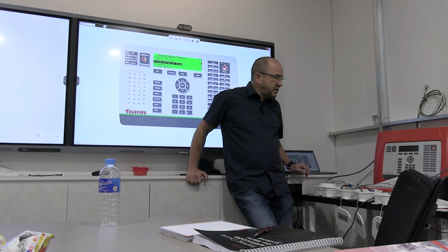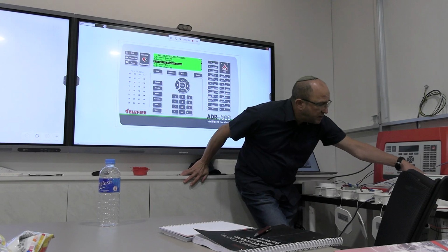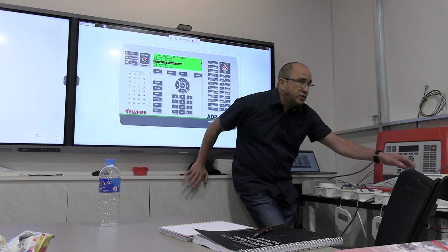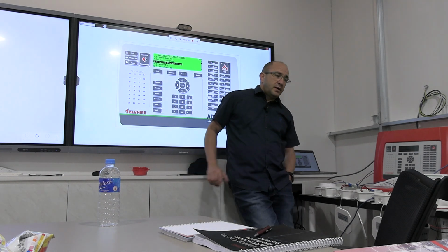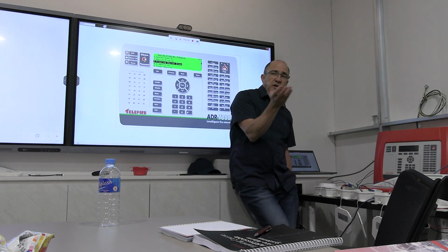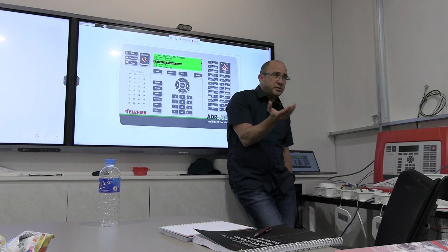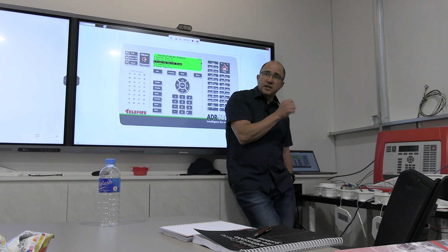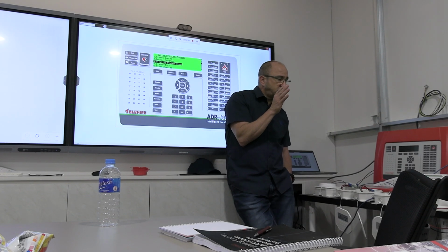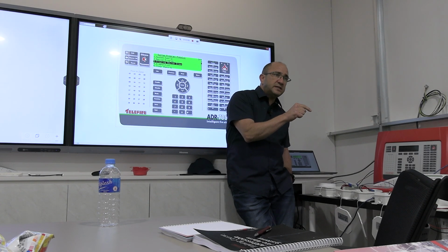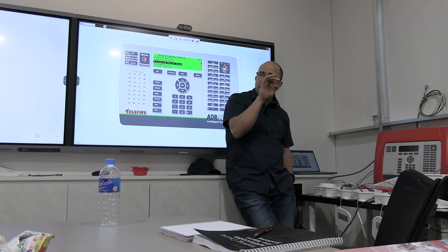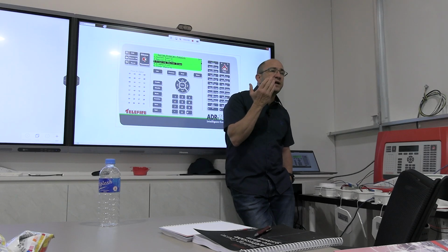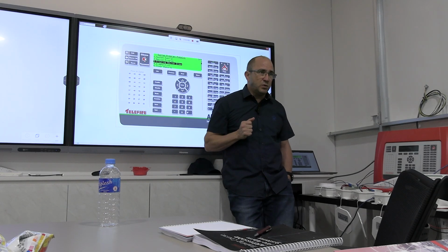So what we suggest is this product, which is called ADR-7000, Addressable Disable Unit. We put it wherever you think you want to put it. It needs a loop, that's it. And it has a key. So the maintenance guy, whoever is in charge, will turn the key, press disable, and it will disable only the devices that can be affected by that pyrotechnics, smoke.